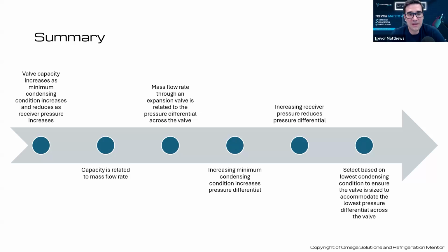Yeah. And then it dives in even deeper when you're using an ejector as the high pressure valve. So yeah, there's so much on the design. And I think the big thing is if you're starting to size these or design these, use multiple manufacturer software. Go into Danfoss, go into Carel, go into Sporlan, go into Siemens, whoever the manufacturer is, the high pressure valve, or flash gas bypass valve, whatever it is, whoever you're using, and go check them out.